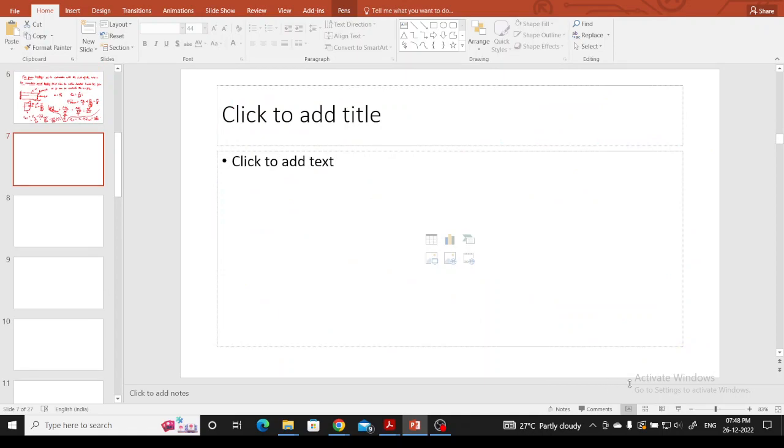Here we will draw the variation of the bending stress, or the total stress, from the top fiber to the bottom fiber. In the top fiber the value is P by 2BD, which is compressive. So let us take this as the negative side and this as the positive side. This is the top surface, and this is the total depth D, and this is 5P divided by 2BD.